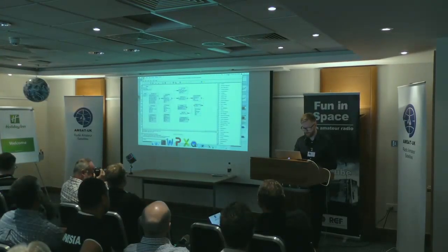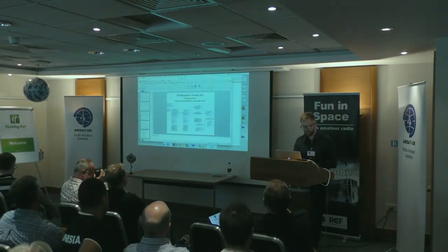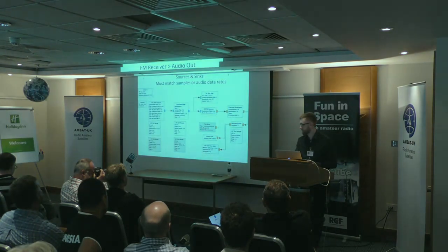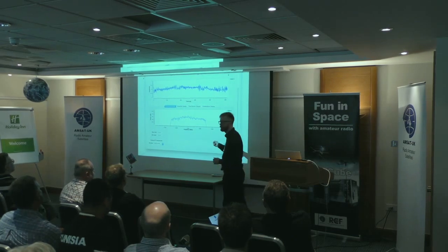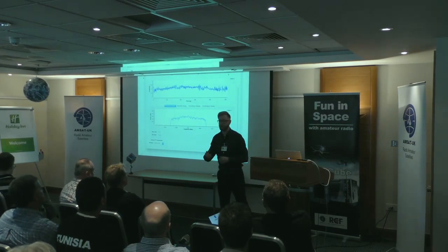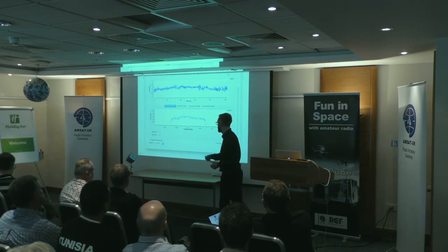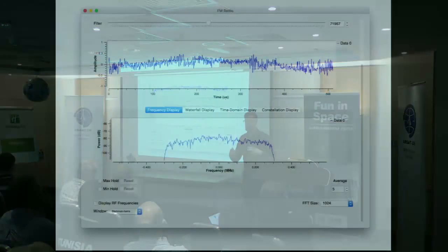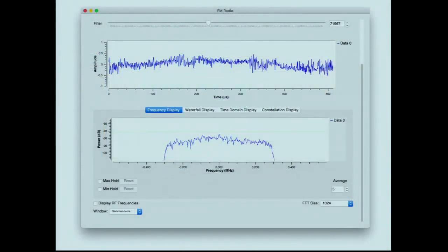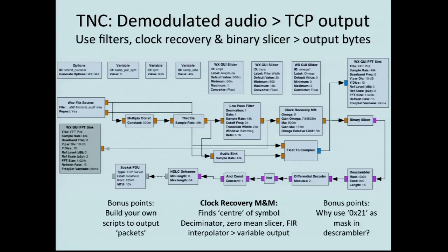So to that point, we've got a simple receiver, and we can get some output. You can use these nice tools, dragging and dropping blocks in to view your signals. Things that you would typically use SDR Sharp or GQRX for, you can make on your own. You can make your own waterfall sink, you can make your own decoders. And that's the next thing to go on to.